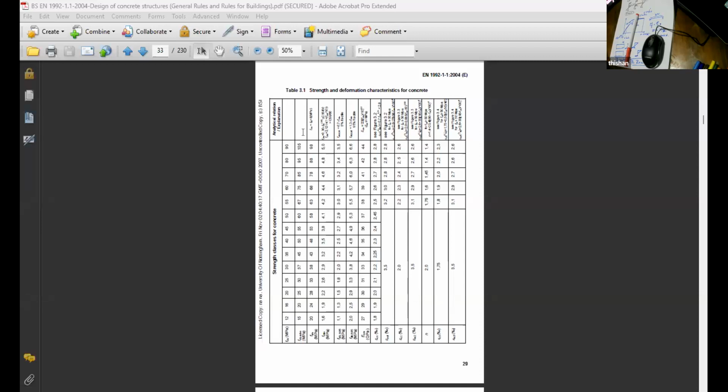What can we do? We can calibrate the PDA results for that particular site rather than using data from other sites, right? Then we know for the specific rock available at that particular site, having its own peculiarities, we have calibrated the PDA by comparing the results of maintained load test and PDA. So once the calibration is done, your predictions from PDA will be for that particular site, and we can be sure what we are doing.